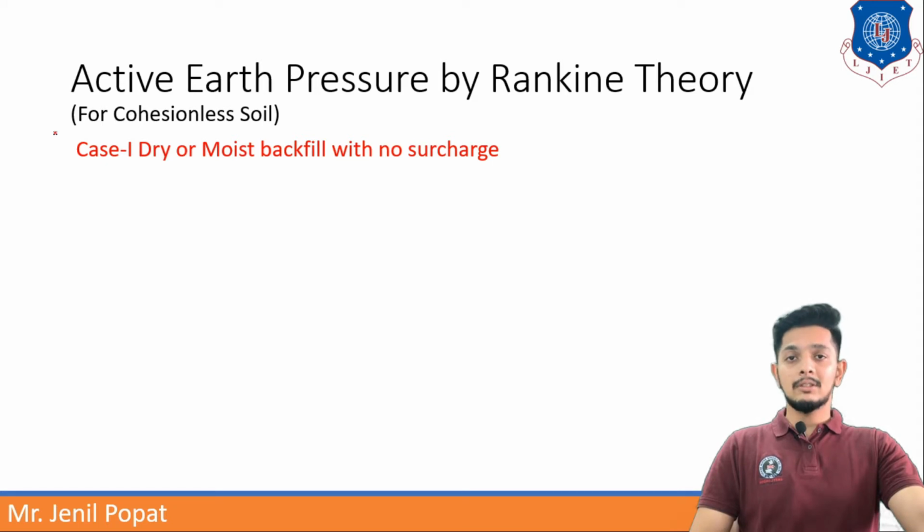You must remember surcharge. Surcharge is what? Whatever the angle the soil is making greater than the horizontal angle of retaining wall, that is beta, the surcharge angle. So here there is no surcharge.